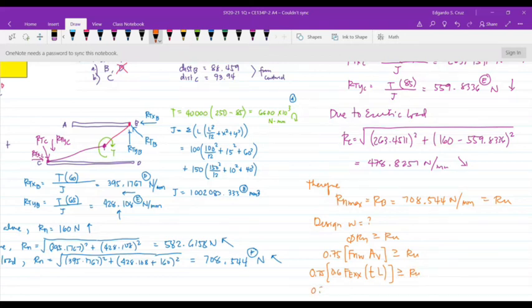Okay, so we have 0.75. Okay, so that would be 0.6 again of the tensile strength. Okay, ano yung throat distance in terms of the size? Diba that is sine 45 degrees times W. And sine 45 is 0.707 and W is the size of weld. Yan yung throat distance. Times the length L. Should be greater than or equal to R sub U. Ayan. So direct substitution na tayo ngayon.